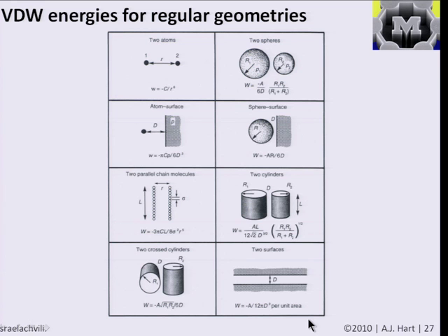And so if you subtract the energy at that distance from the energy at a very far distance, basically how much work you would need to do to separate the surfaces, that can be related to twice what we call the surface energy. So you could consider the same kind of thing as taking a sphere and subtracting out the center of the sphere in a similar fashion.